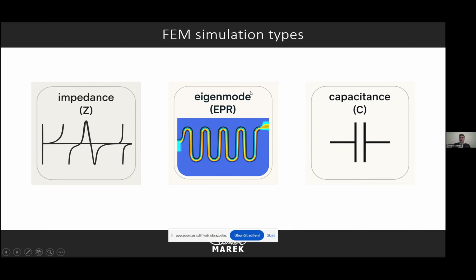Here you can extract your behavior of Josephson junction, and you can also simulate electric fields. And here is capacitances. From your circuit, you can also extract parasitic inductances or just inductance of a meander or capacitance of islands from transmon qubit.